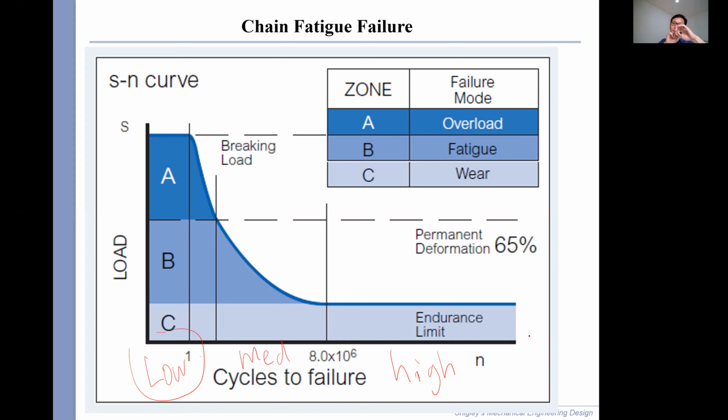Karena kan the bushing got worn out, right? Jadi kalau tadinya ini pinnya and then ini bushingnya. If you imagine the pin getting smaller, the bushing, I'm exaggerating of course, the bushing is like this, then the center to center pitch actually increases and the overall chain actually lengthens, nanti dia mulai ngedoyot gitu kan ya, because it lengthens. Oh, berarti karena abrasif gitu Pak ya. Jadi karena gesekan dia berkurang.